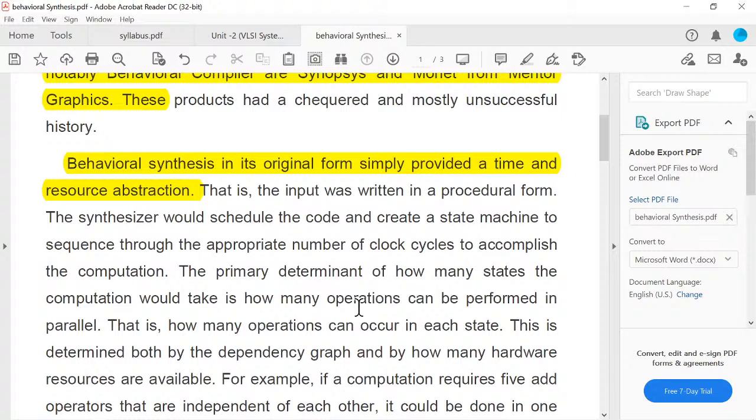We can start from the gate level instead of the transistor level. When we start designing at gate level, it means that we implement a circuit by using digital logic gates instead of transistors. If we implement the circuit by using gates only, it falls under the category of gate level synthesis. When the number of transistors is very high, we cannot start our designing process at the transistor level, because the number of transistors is huge.